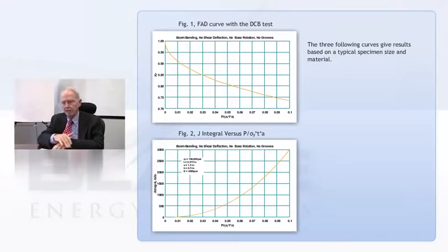And why is that? The why is that is that if you include the shear deflection with the other restrictions of the problem, the crack doesn't open as a cusp as it should with the Dugdale-Barenblatt solution. It opens with an angle. So that won't work. So what can you do? Well, one way out of this is you can look at the region near the tip of the crack, and you can work a little elasticity problem that puts in rotational resistance for the sample, the test sample, beyond the crack. So you put in a little elasticity back there, and it's not too important how you do it. You got to get a reasonable answer, but it's a relatively straightforward elasticity problem to get an approximation to.